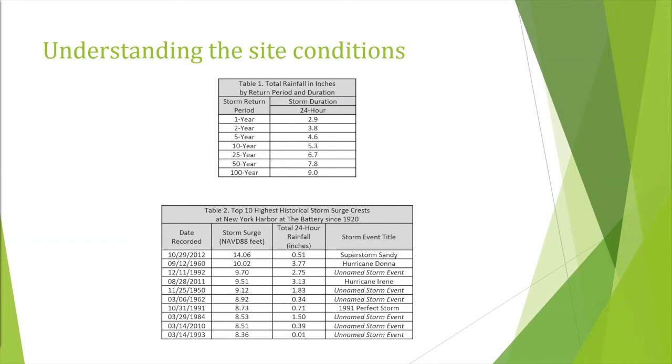So we kind of had to lay this out for them so they really saw, are we putting your money to the best use? The wall, the detention, underground detention, and we're talking about an active rail yard. So putting underground detention and pumps just to deal with 100-year rainfall, it became a space requirement that we just could not accommodate for them. But also, when you look at it practically, we're not saying that an event like that could never happen, but you've got to rely on the data and understand that they're not always in the same plane. So this really helped drive it home that, if you look at it, Sandy wasn't even a 1-year rainfall event.